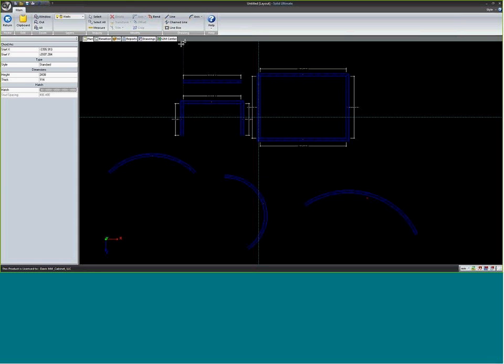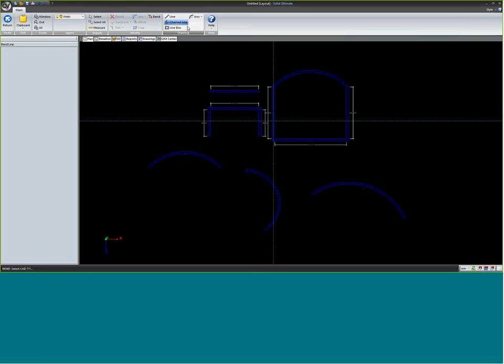But if I do have to do a curved wall, I typically don't use this tool, although you can if you want. Typically what I'll use is back here on this modify section, I'll use a bend tool. So just click bend and then grab a wall and bend it out to whatever size I need it to be. But either one works. Notice on the modify tool, I do not have access to most of these. They're grayed out. I can access bend right now, and that's all.